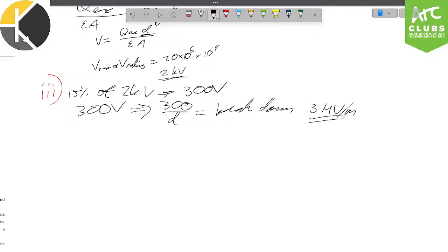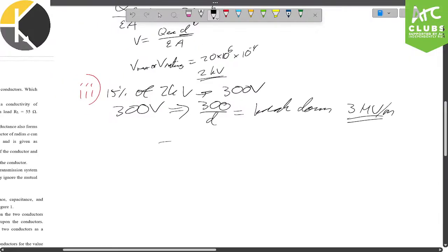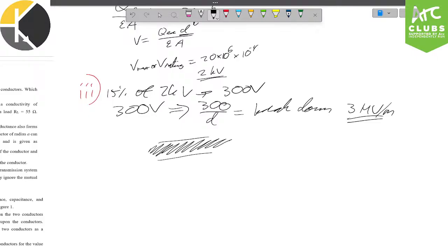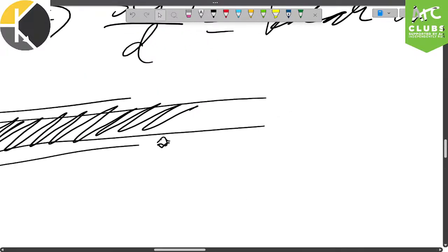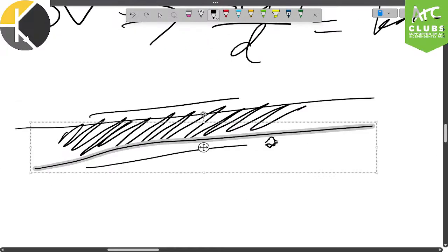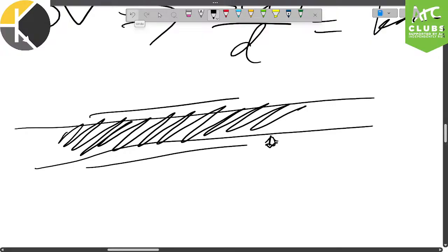So we can identify that potentially within our capacitor, there is some manner of material inside of it, which is given by our paper, but then there may be some minuscule gap that is given by air. And so we're experiencing a breakdown inside this air, which is damaging the capacitor, and it is breaking. Okay, so that is the understanding that is wanted to be derived from this question. We call this little distance of air, let's call it dA.